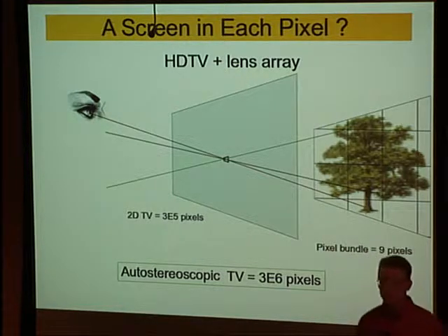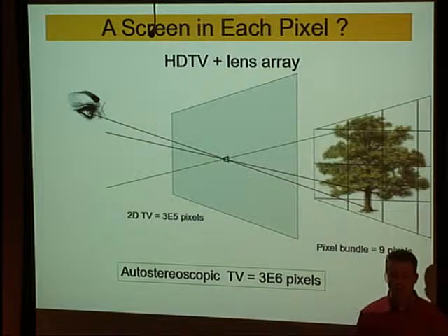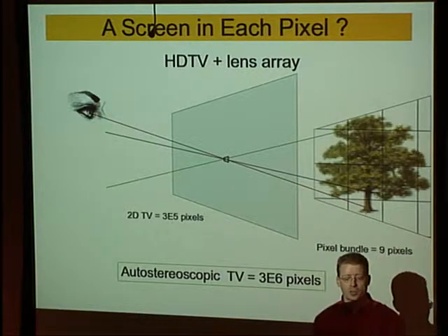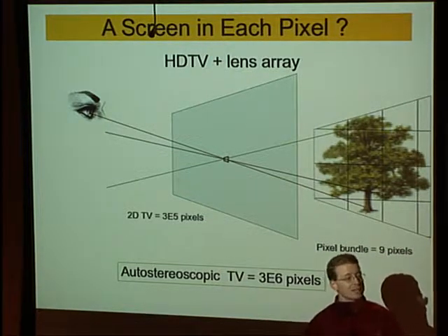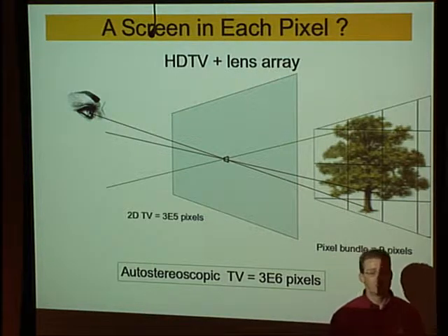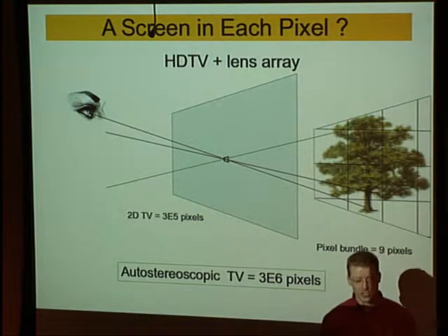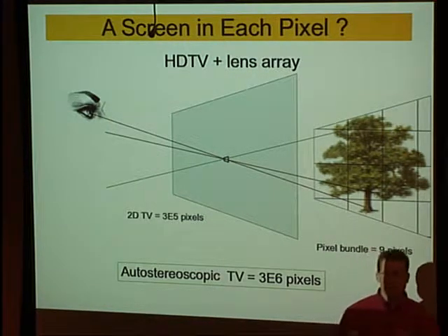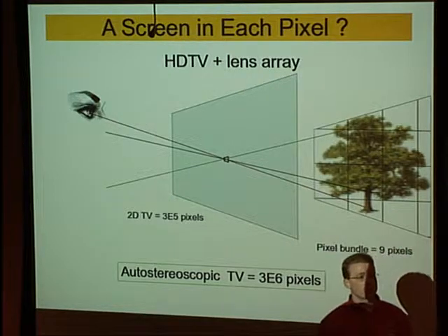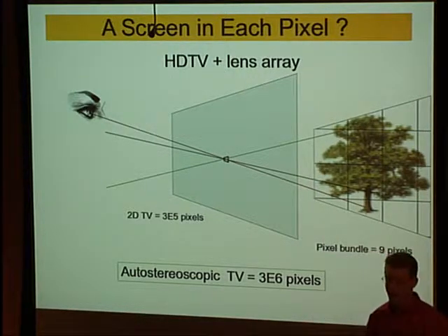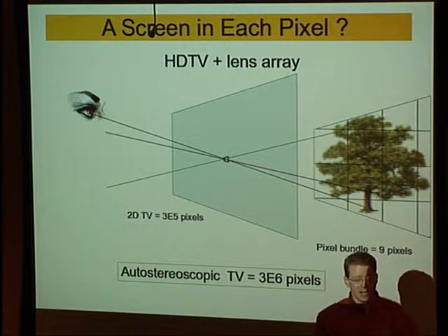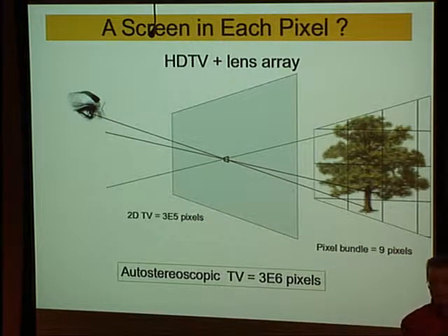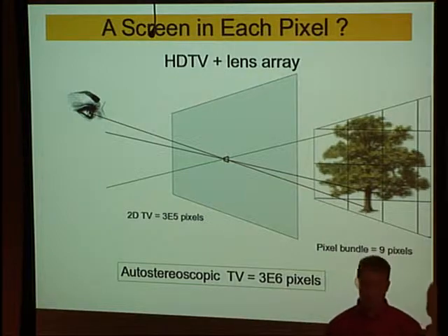The big question, though, is how many pixels do we need in a stereographic display? Because with too few pixels, like 10 views per aperture, you have the actual autostereoscopic TV that uses a lens array in front of a high-resolution display. This is like integral imaging. The problem is that when you move, you see some dead zone where the perspectives are not correctly reproduced. It is inverted, actually, and this is really disturbing. And motion parallax in such a system is not continuously rendered. It jumps from one view to another. It's not a smooth transition as you expect.